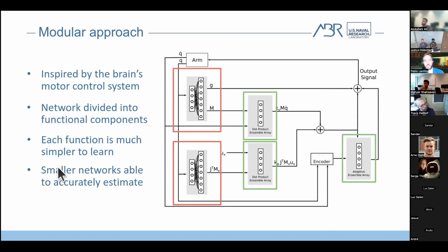This is something that is very weird from the point of view. Oh, yeah. Well, gravity is only a function of joint angles. What this is representing is not the gravity itself, but how gravity affects the joints. So the input is the joint angle. Yes.